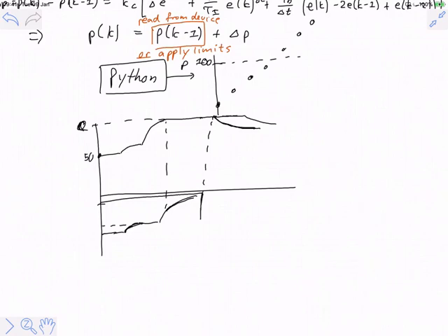And I want to make sure that everybody understands that this difference is not some magical property that just emerges by itself when you take the derivative of a controller, right? You have to actually wire it all up. And you could do that with the position form. Because I think a lot of people, when you just read the book, it seems like the velocity form is so clearly superior to the position form that you're almost angry at me for even teaching you the position form. But in terms of real practicality, there is very little to choose between the two.